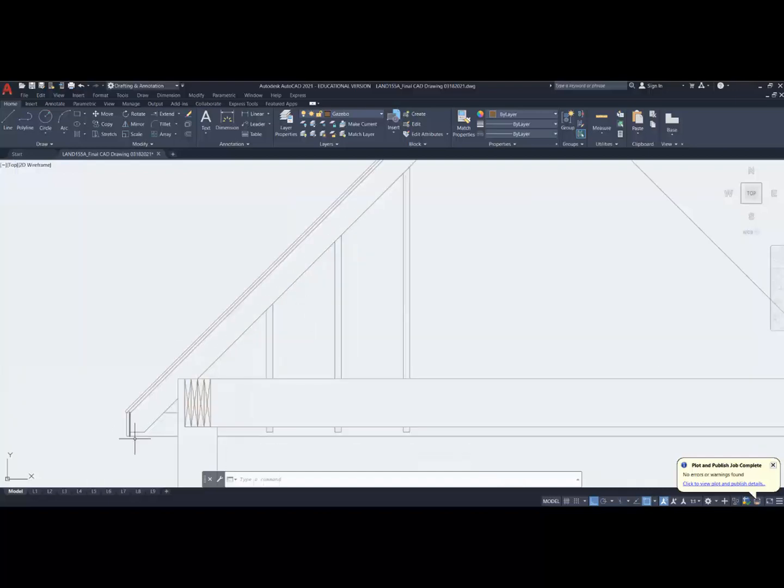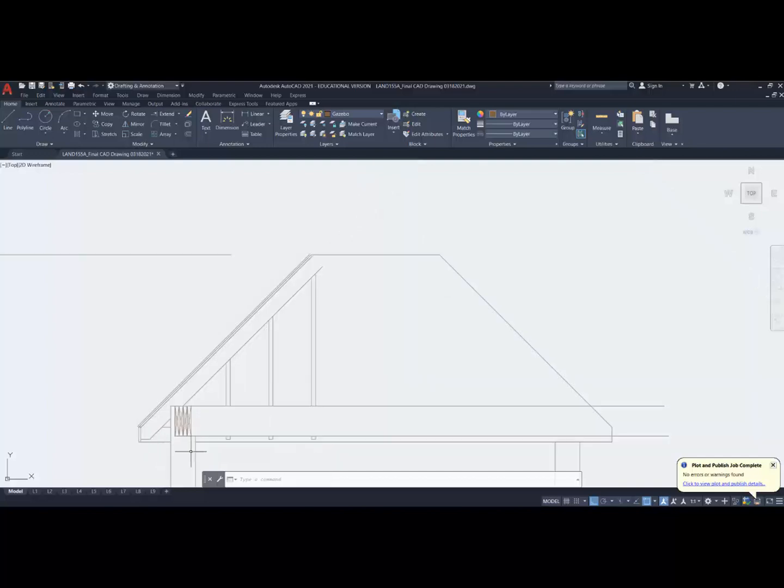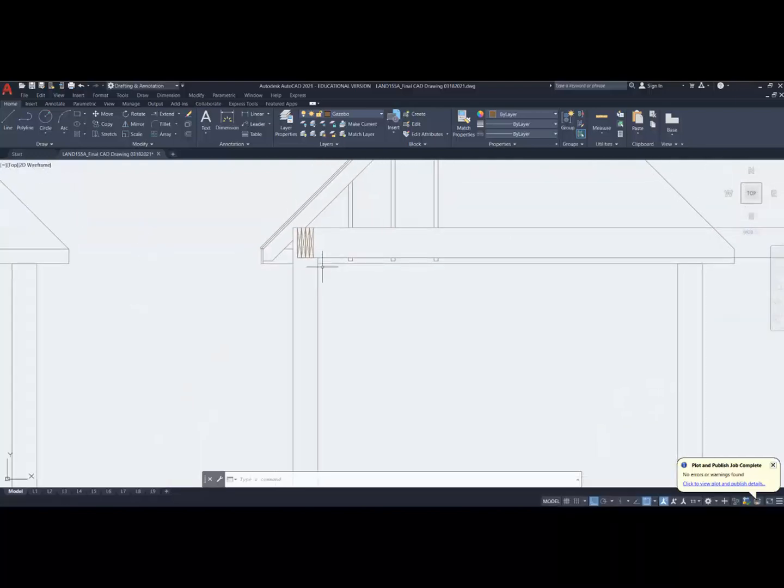This is what we're going to see inside as it's being built. The beam is heading towards us. The post is going to be notched out. The beam along the back wall is going in that direction. The ceiling joists that are sitting on top of this are going to be notched out. Therefore, we don't see it until it sticks out. The bottom of it sticks out to the point that we've cut it here. And that's how you draw the section of the top half of it.